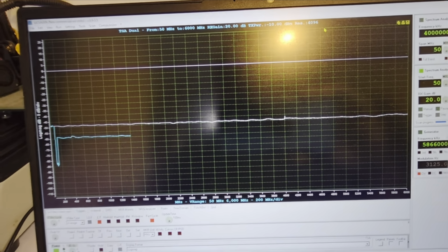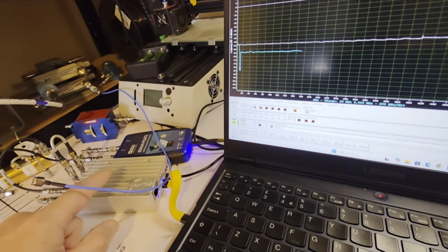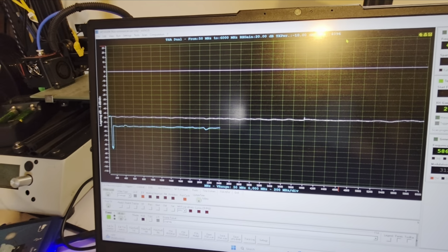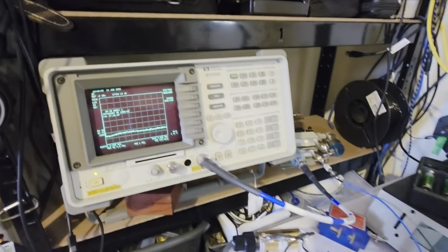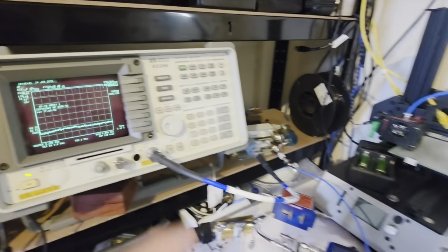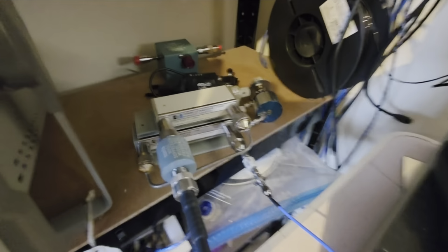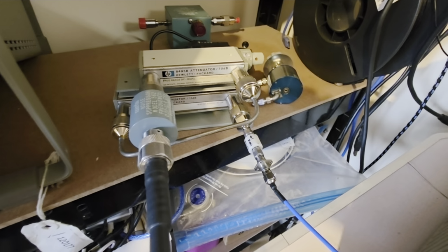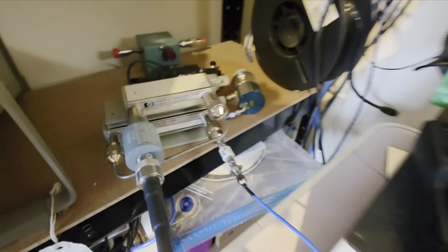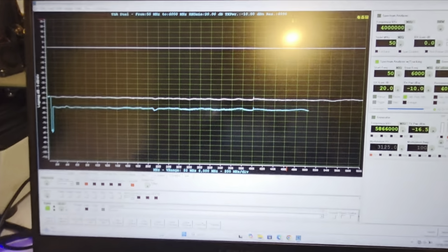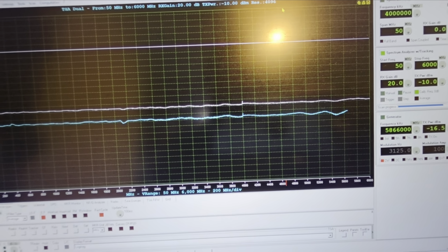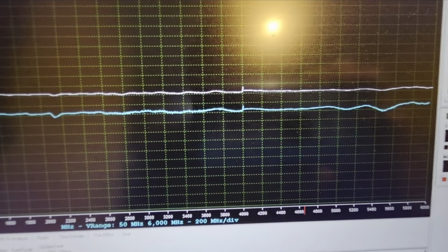This is the first run that I have with the VNAs and the SDRs calibrated, because I just got this three days ago. This is the first thing that I did with it, calibrate this. They are not perfect because I have some data attenuator, DC block. I used all that in the calibration, so maybe I didn't compensate properly. Maybe it's half a decibel off. And at 70, it's still valid.